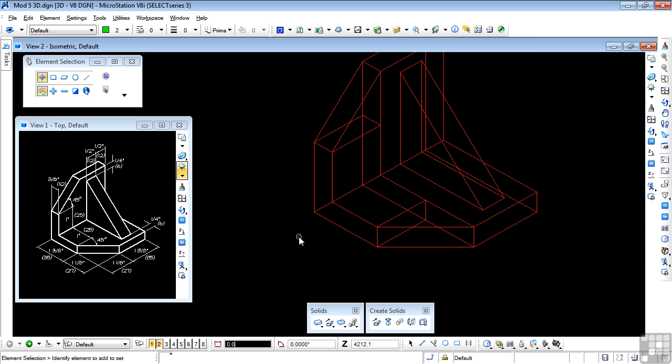So that's a slightly tricky maneuver, but if you know how the rotate tool works, then this makes sense. Just keep in mind that it's the centroid of a 3D element which is being rotated. Try it with a construction line too, and try it too in the right view as a two-dimensional view and see how that works for you.